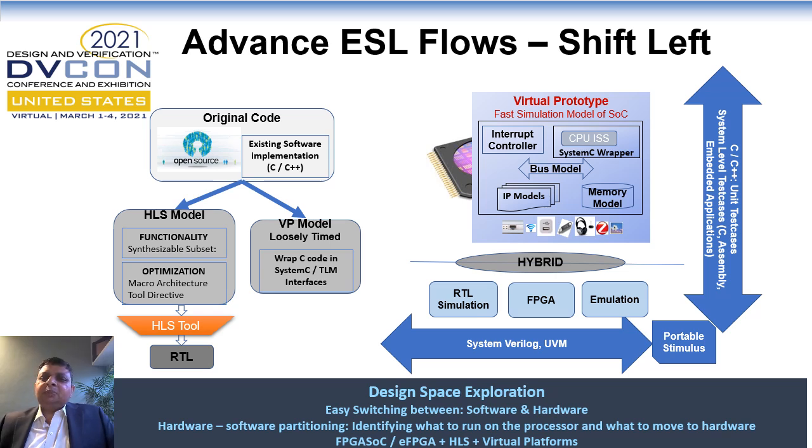With these kinds of setups, we get complete flexibility that throughout the life cycle of the project, different teams can choose, depending on what portion of the design is already available in RTL and what portions we have as SystemC models. So different teams can choose different kinds of technologies to enable a true verification continuum from IP level to SoC level, right from the beginning until the end throughout the design and verification flows.